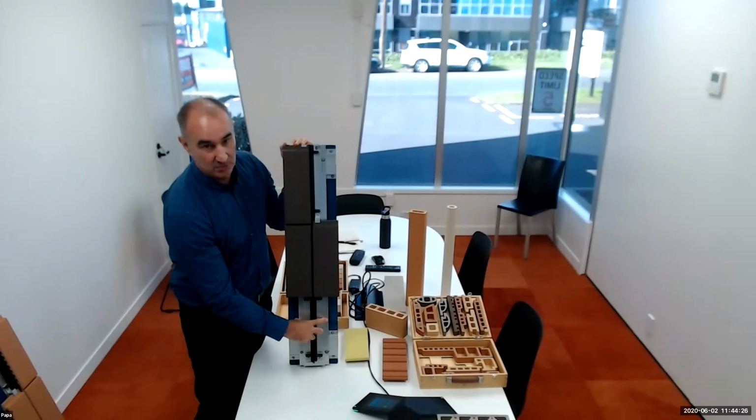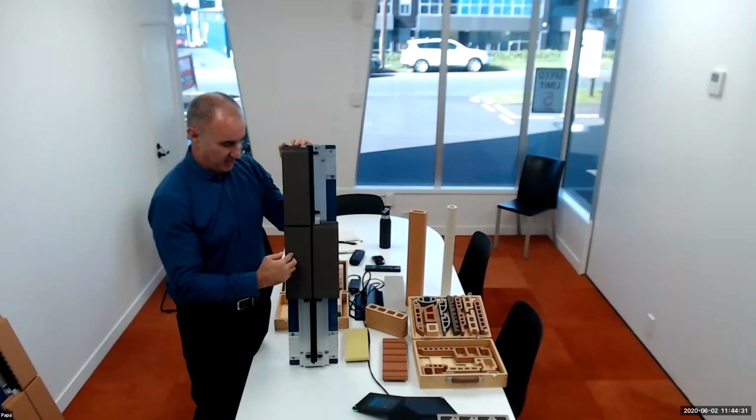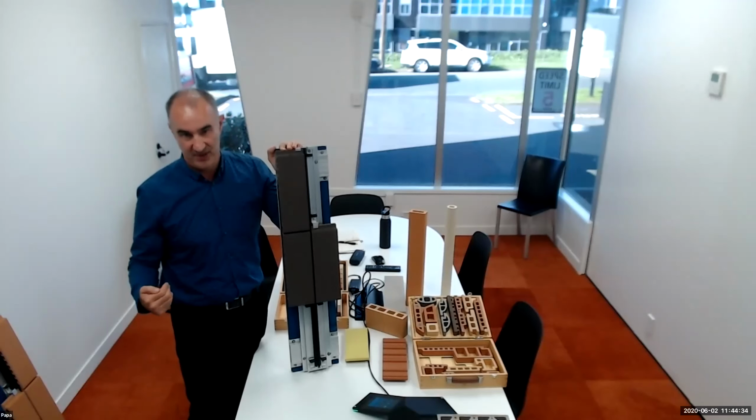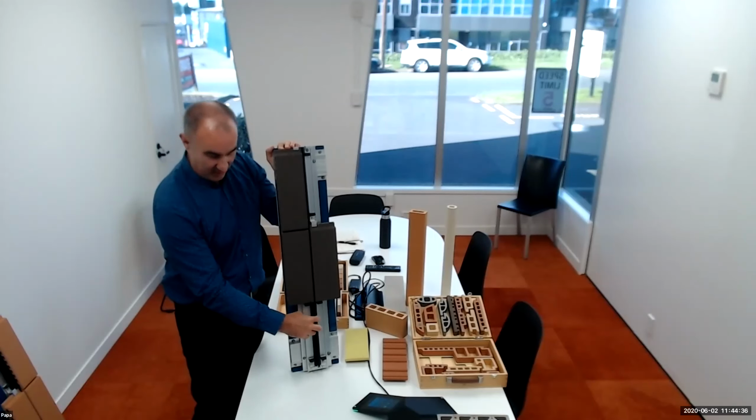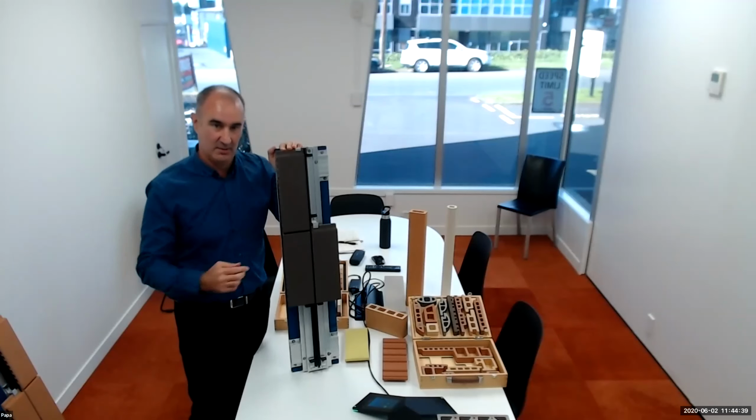Sorry, can I ask a question? Yeah, go for it. Does that mean that this unit you're showing us repeats every 40 millimetres? Like, do you need one vertical aluminium backer for every tile? You understand what I mean? Yeah, so this vertical rail here is only on every vertical tile joint. So let's say the span of your tile is 1200, 1500, 1800, whatever. You'll have one of those at every joint. But the tiles will express themselves as a single 1200 long tile? Yes, correct.